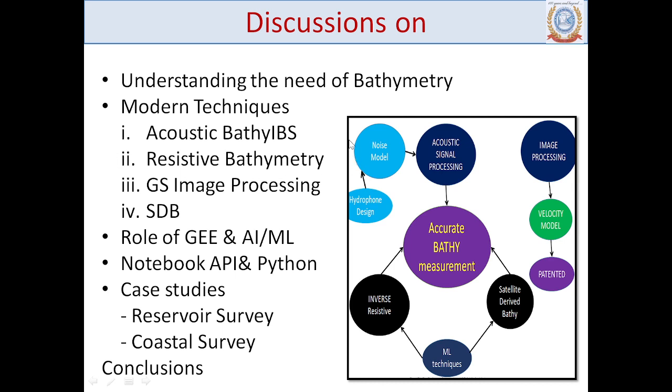By this method, you are able to see the sedimentation layers below the bed of a reservoir to a depth of more than about 10 meters, based on research publications. And you get an idea about what type of sediment layers are deposited. This gives you an idea for the capacity assessment as well as for planning the dredging solutions.